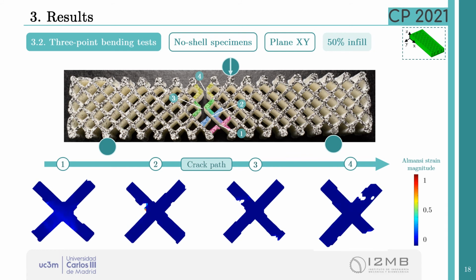In joints 1 and 2, there is much tensile strain before the fracture. Note that this high plasticity appears in a side of the joint, and we will study this failure in the next slides. By contrast, the strain in joints 3 and 4 is lower and the fracture was immediate. So the digital image correlation almost could not capture previous steps. Also, you can notice that the strain in joint 3 is the lowest because this point is on the neutral axis before the crack formation.